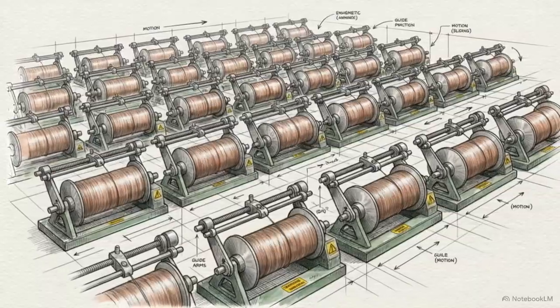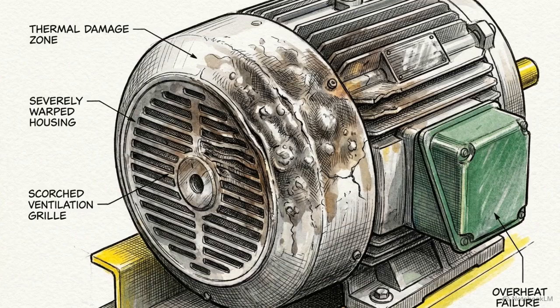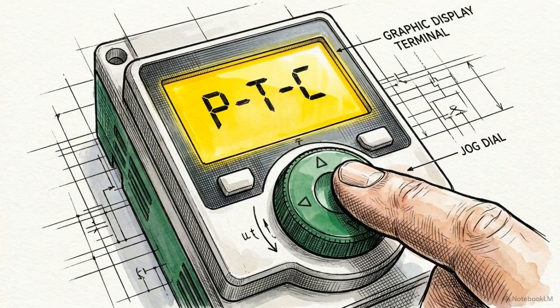Operating complex machines on a hot factory floor creates significant thermal risk. Extreme heat is a primary cause of motor failure and hardware damage. The drive's defense lives in the Fault Management menu. Navigating to the PTC section allows you to configure thermal monitoring parameters.